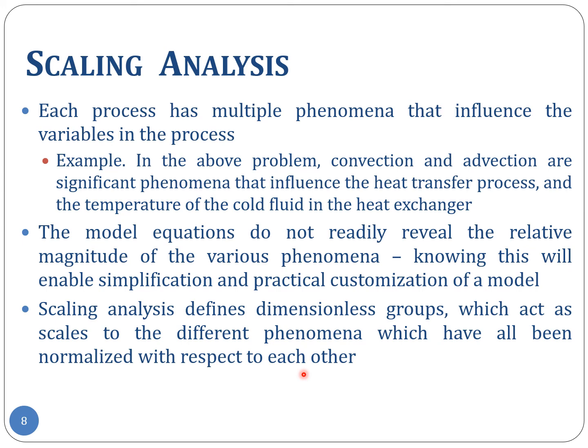numbers. In case of dimensionless time, you may have 1 tau, 1 t bar, 2 t bar, 3 t bar, and so on. So a few values. And then the right hand side has lambda times theta h minus theta c. Both theta h and theta c vary pretty much from 0 to some small magnitudes. So it is basically the lambda that determines: if the lambda is very large, the right hand side dominates. If the lambda is very small, the left hand side dominates. The left hand side is convection, the right hand side is heat transfer from the hot fluid to the cold fluid.